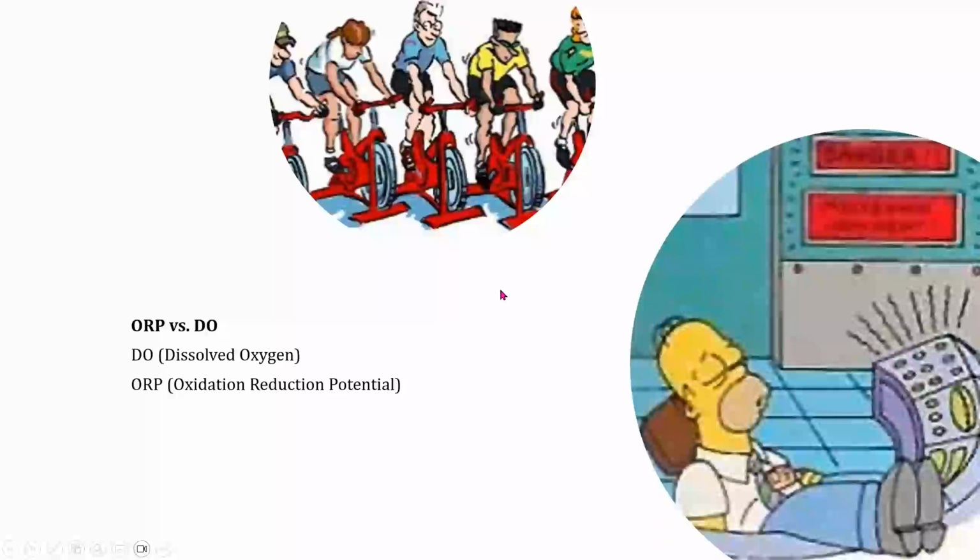And then the other big advantage, and it really gets important in phosphorus removal, those first two steps I talked about happen in zero oxygen environments. So a DO meter doesn't tell you how far into that environment you are, whereas an ORP will not only tell you how hard organisms are working to breathe free oxygen, it'll tell you how hard they're working to breathe the oxygen that's connected to some other molecule. And that's important because we want them to be breaking down the right molecules. So we need it ever more septic for phosphorus, for the VFA production, than we need for the nitrate production last week that I talked about. And the best way to monitor the environment is with an ORP.